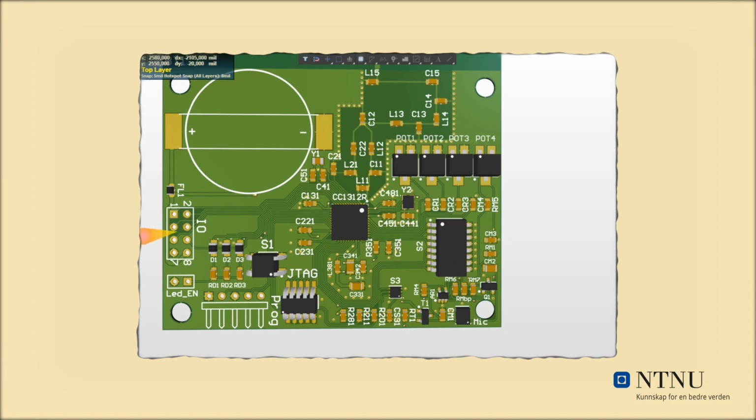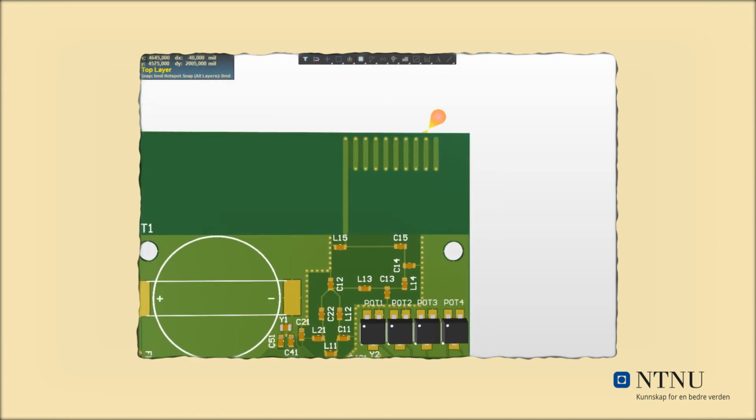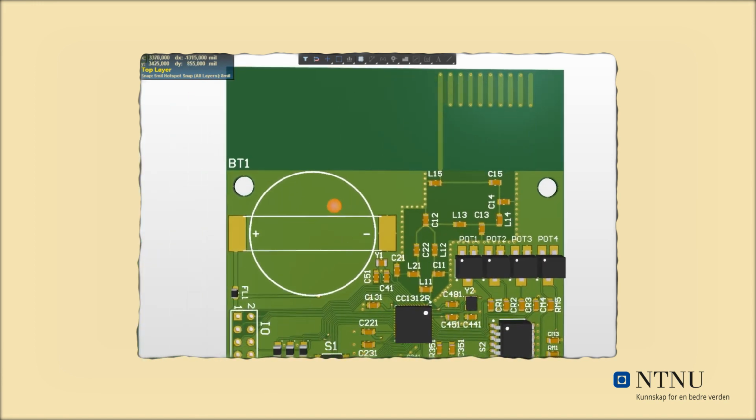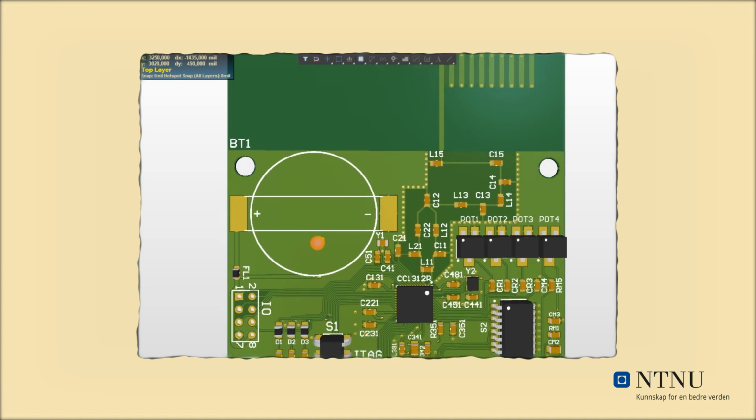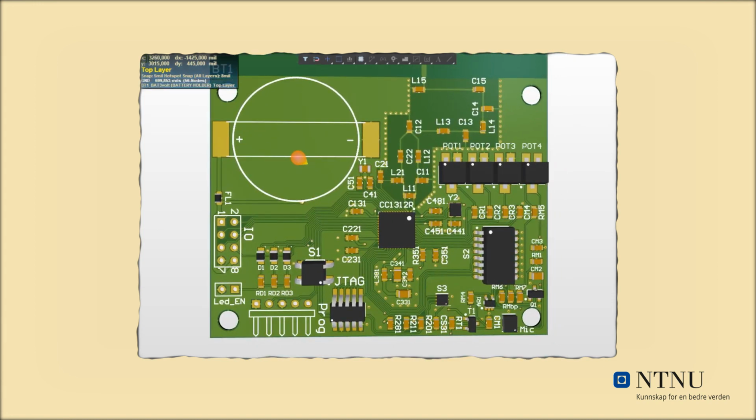We have 8 dip switches. 6 of them are used for each of the I/O here, and one of them is used to select which accuracy to use for the brightness sensor. We have a DN038 antenna, a PCB antenna, and we have a CR2032 battery, which is a commercially very available battery. It has a lifespan of about 10 years in our use case, and we have a custom-made pairing port.